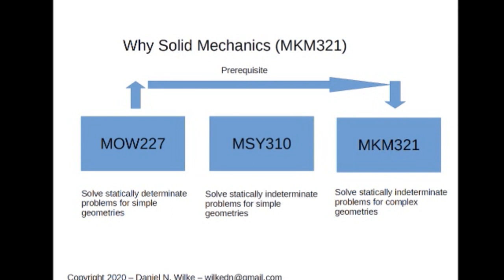They cover all of this beam theory, deriving it in a different style to what I've done, but they go through exactly the same material and talk about linear superposition to solve statically indeterminate problems, or linear superposition to solve complex loading cases, so that you can leverage the beam deflection tables to a large extent to help you to be agile in terms of design and verification. Okay, so that's just a reminder.